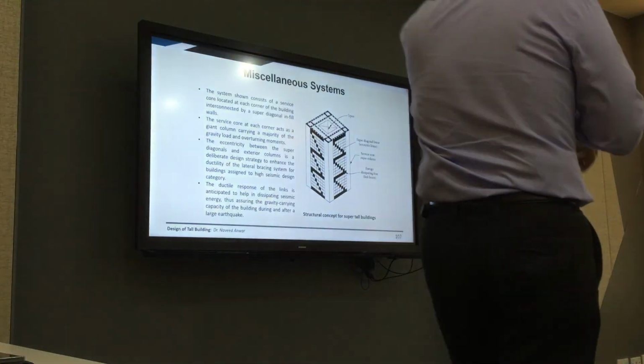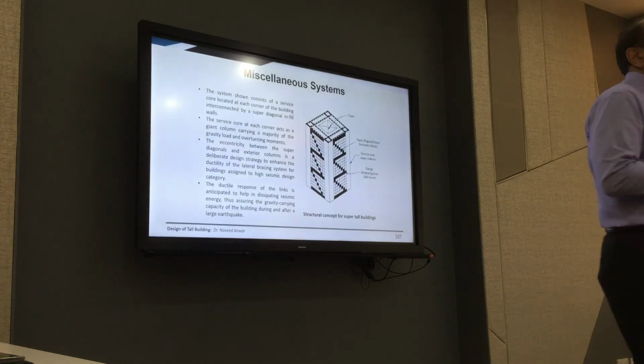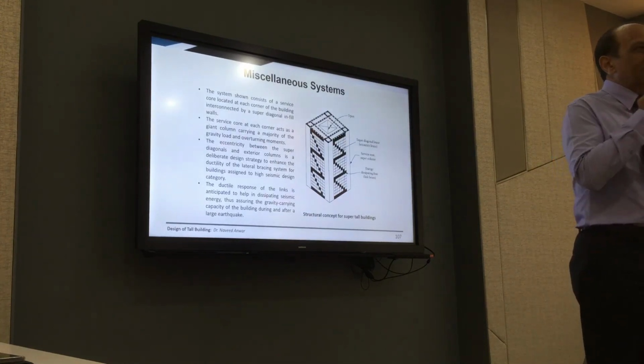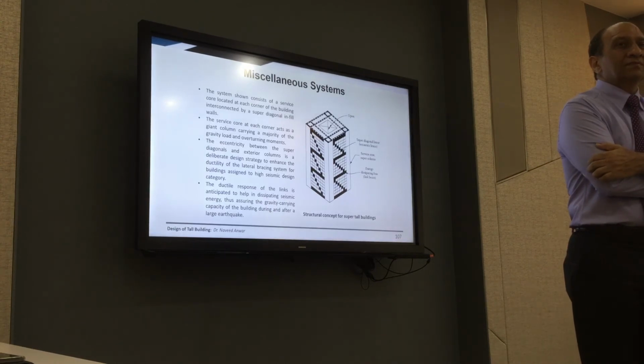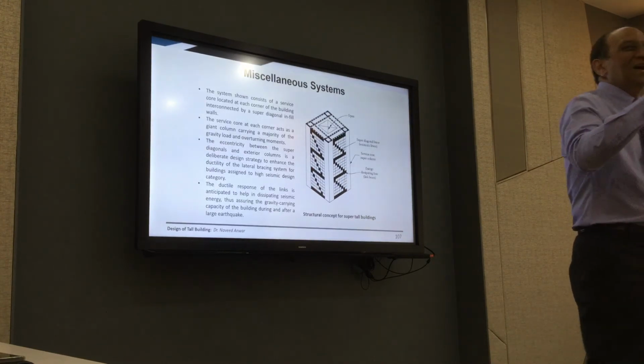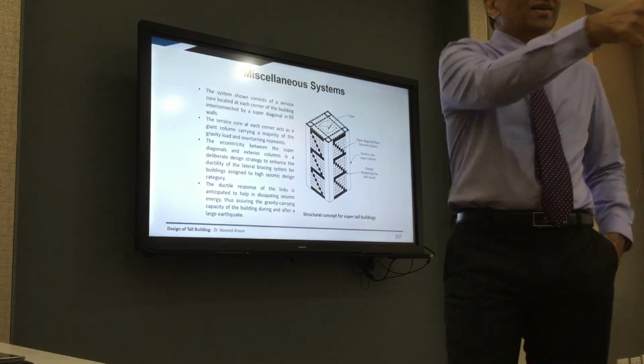We have no time, but I still want to ask you, what did you learn or did not learn today? Very quickly, 30 seconds each. Important observation today: the structural performance can be improved by converting bending moment to shear, and also the lateral deflection can be far reduced by the outrigger effect. You have taken the comments from everybody else. I mean, others will. Okay, next one.